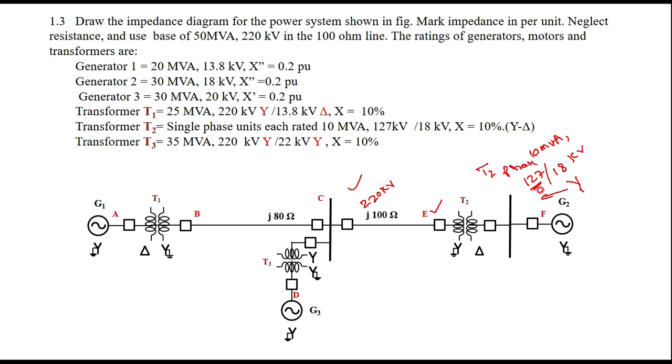Then how to calculate if all the three transformers are connected in star mode on the transmission line side, the line value we are getting here is root 3 times 127, which is around 220 kilovolts. So this 220 kilovolts can be matched with the high voltage transmission line.